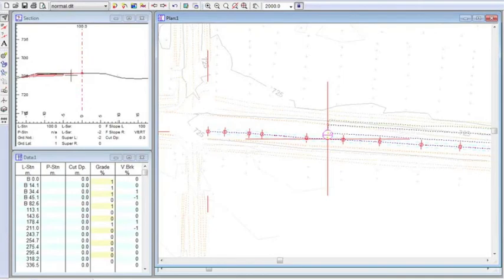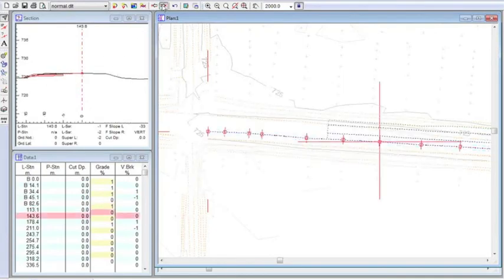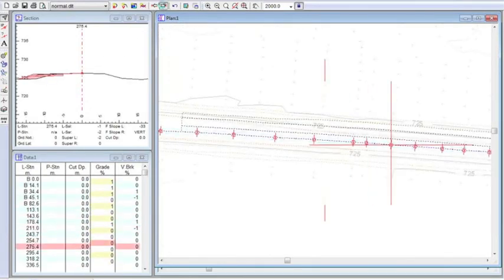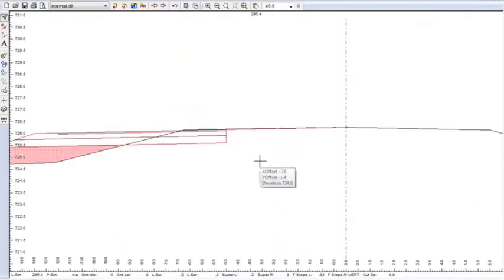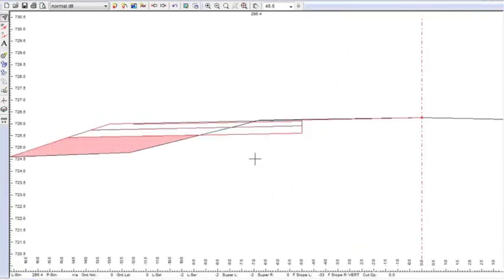The road is already wide there, but as we move along the alignment, you can see that the road isn't very wide, and now my widening template is extending it to 2 lanes from 1 lane. And it's doing that by cutting away the old shoulder and refilling it with these well-designed engineered materials. Great.